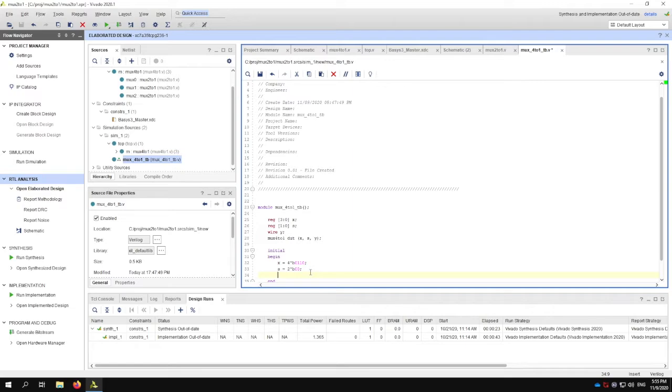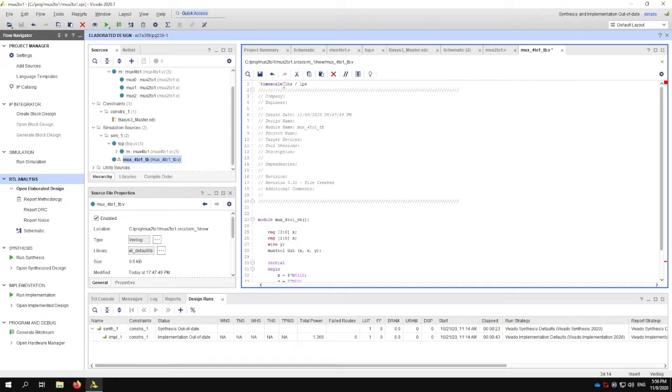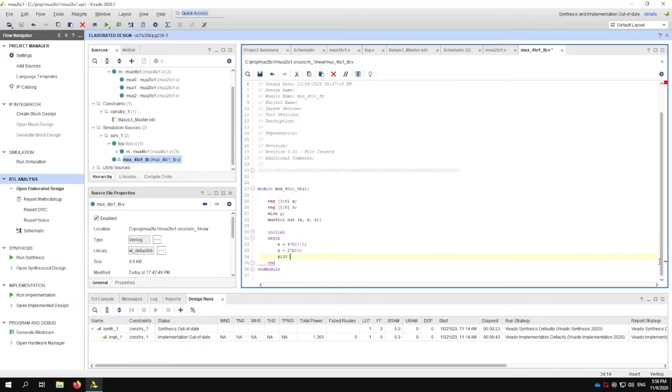So moving on, I'm going to do something else. Now I want to say retain these values for X and S for 100 nanoseconds. So at 100 nanoseconds, or 100 nanoseconds later, that's what this means. Hashtag 100 means 100 nanoseconds later. How do I know it's 100 nanoseconds? Because look at my time scale. My time scale here is 1 nanosecond. When I refer to hashtag 100, I'm referring to 100 of these 1 nanoseconds.